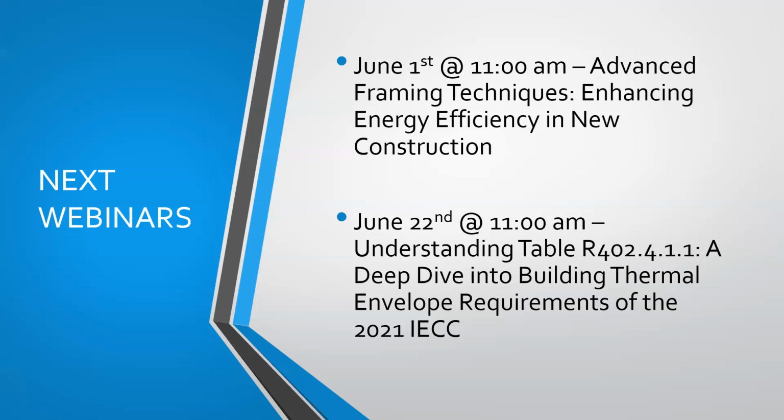So much of that is going to be with our WRB, because again, stucco is just a decorative detail that's water resistant, no different than brick or stone or anything else. Texas A&M has a study where they put up a brick wall between two people, spray it with a garden hose, and within 30 seconds, water's on the other side of the wall. So again, these materials are very porous and going to allow water through. What we really have to be so concerned about, even more than the moist cure and everything else that they're not doing, and leaving out the expansion joints, all of that's great, but it's all about the WRB and the flashing details. No matter what our product is, that's what we really have to get more in tune on.